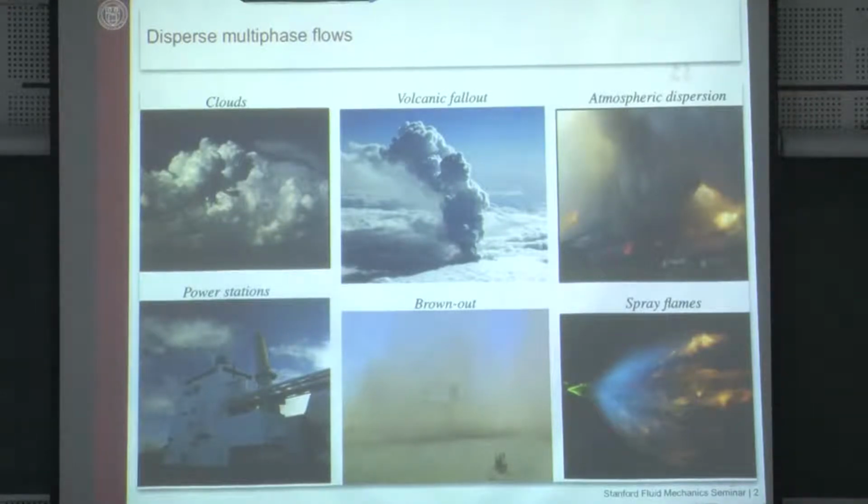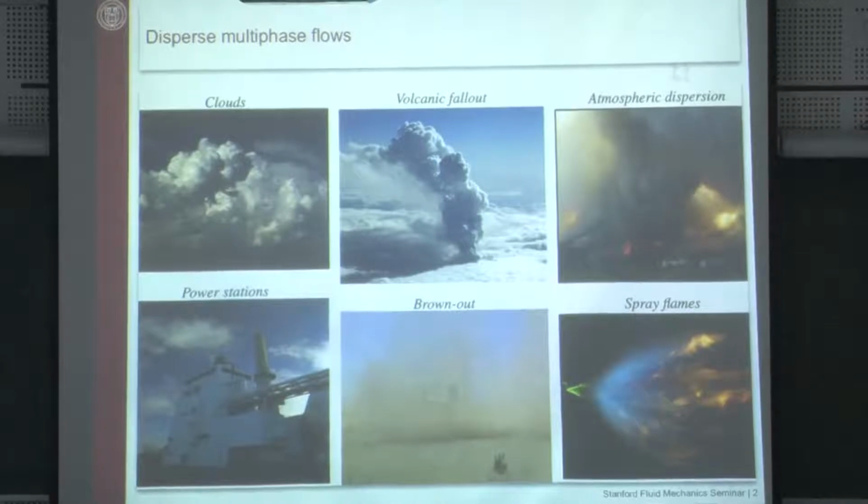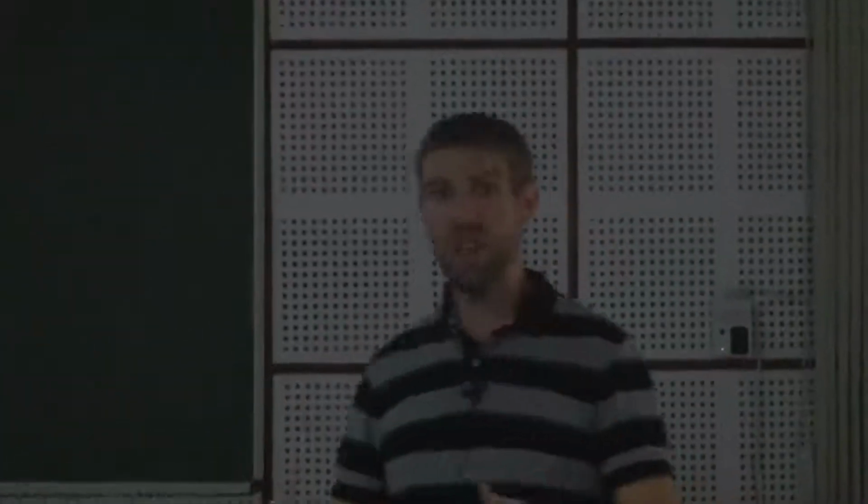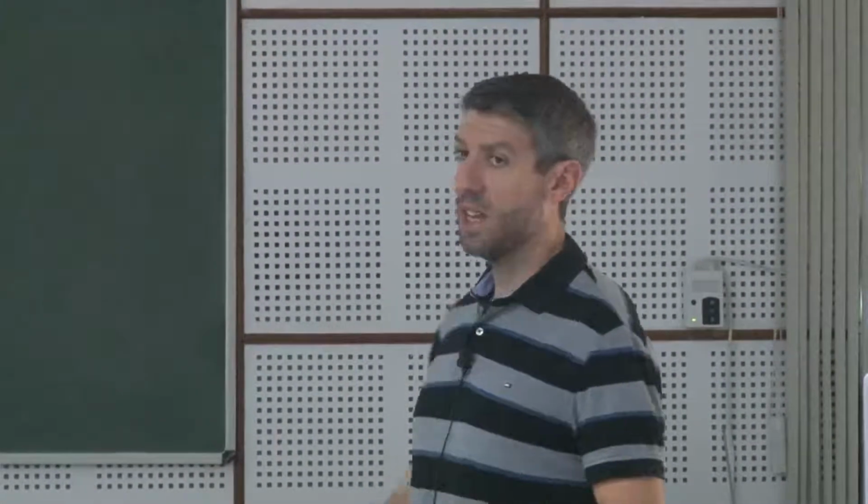You know how to operate the transformation on a small scale, so the unit transformation is something you control. It's a multiphase process that you can predict. As soon as you try to scale it up to several meters height and a meter width, you try to intensify the process. This is where suddenly the mixing changes, the multiphase flow behaves differently, you have different dynamics, and all your models fall apart. You build something like that, it ends up behaving in a way that's completely different from what you had predicted in the first place.